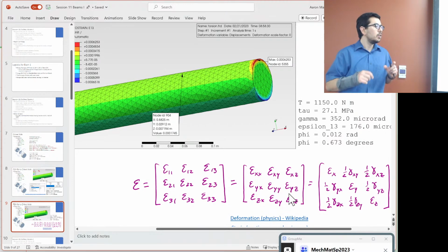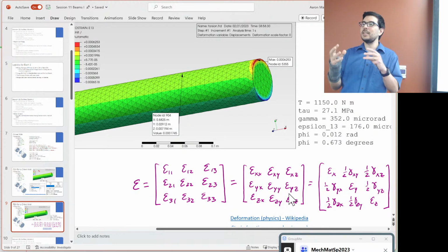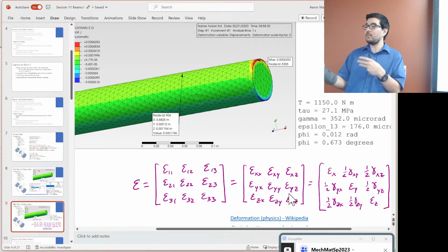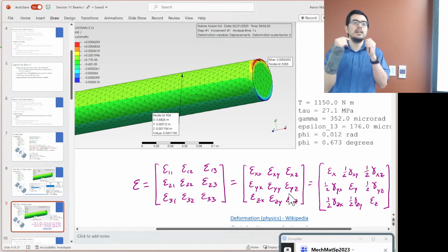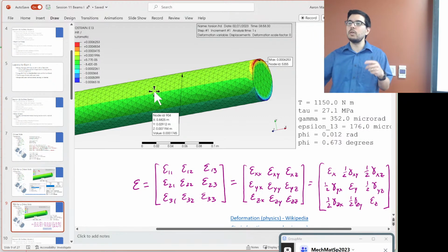On an assignment, you'll get an opportunity to put a beam into FreeCAD and then into PrePoMax. When you take the screenshots of your result, if we ask for shear stress, then do a query on an element and show the value, such as S12. Make sure it's clear that the element is showing the particular quantity, whether it be shear stress, shear strain, or rotational displacement.